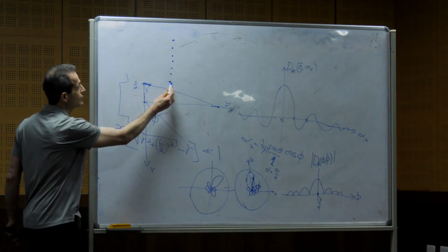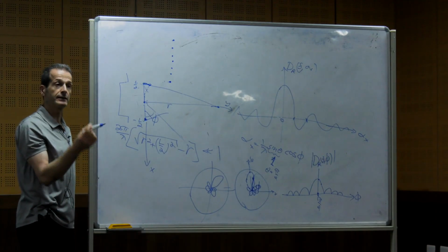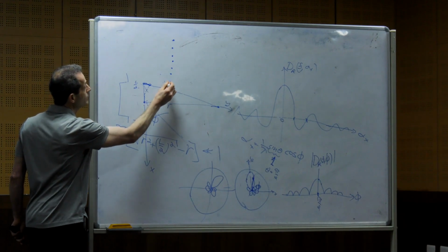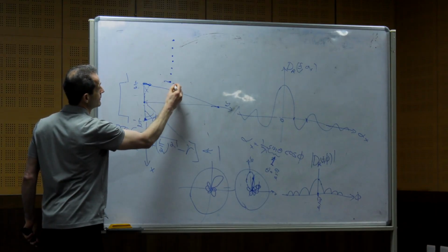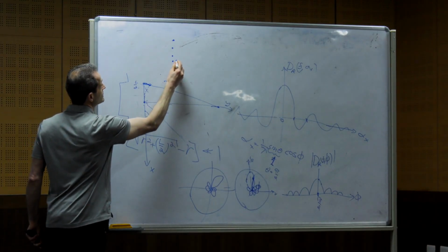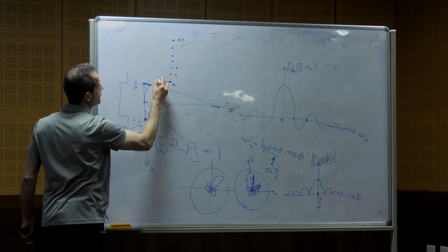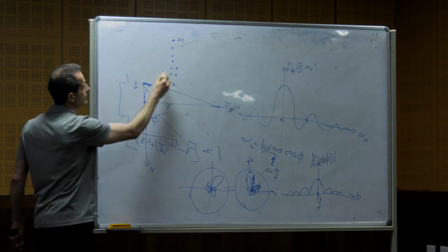I can multiply it with a certain complex number that includes magnitude and phase. Let's say this is sensor number 1, 2, 3, and so on until M. Here I will multiply it with W1(f), because it depends on the frequency.